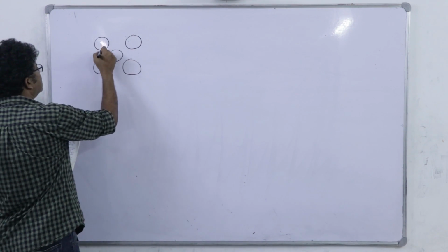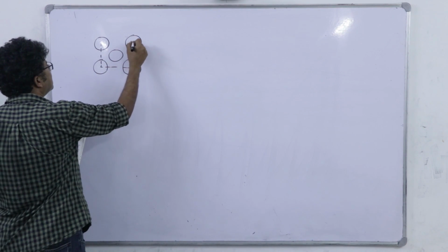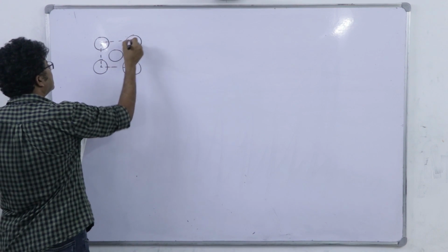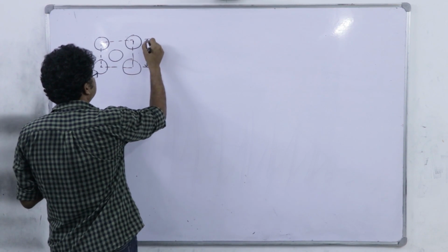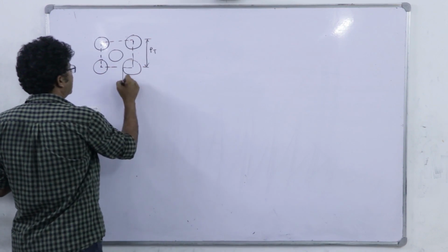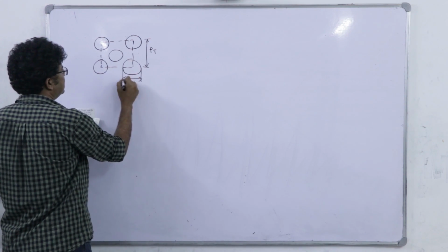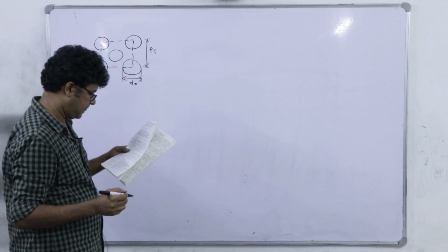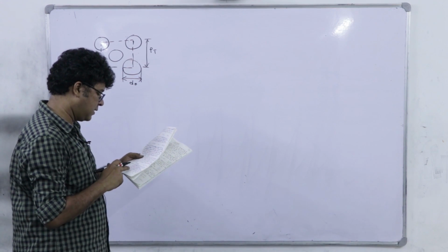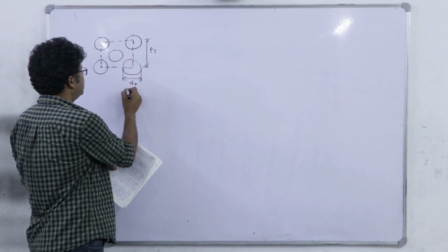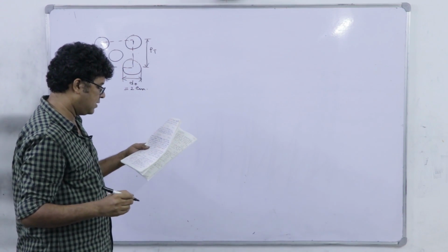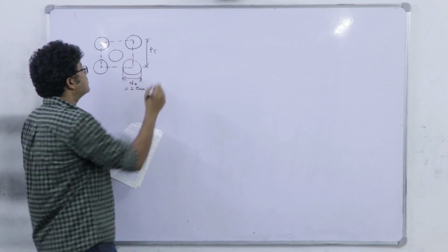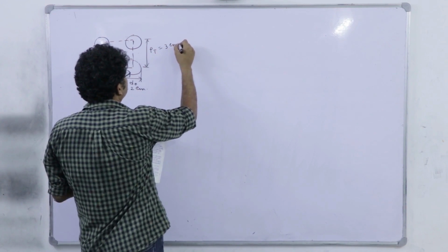So this tube to tube, center to center distance is PT, and the diameter of the tube is D0. That's given. All the tubes have an outer diameter D0 equal to 2 centimeter, right? Whereas the tube pitch is 3 centimeter.